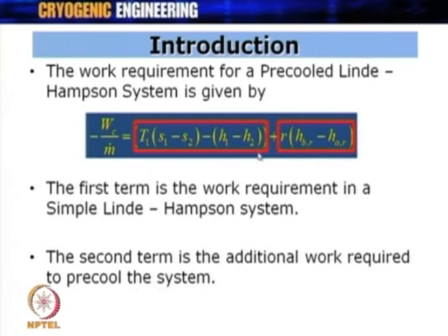So, the first term remains the same as long as the suction pressure and the pressure at the end of compression remain the same, but this is the additional amount of work that has to be done, and that comes due to the pre-cooling circuit in the pre-cooled Linde-Hampson system.